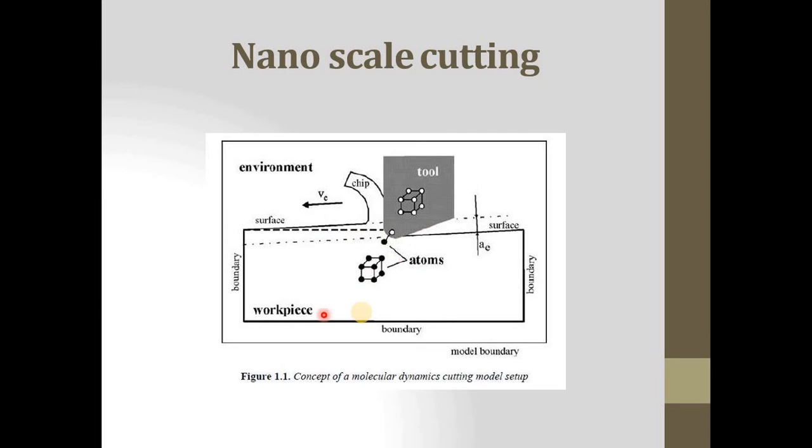So consider a crystal size. We're considering the crystal size of typical metals, which ranges between a few tens to several hundred microns in diameter. A single crystal, or what we call a single crystalline workpiece structure, represents a reasonable material structure for nanoscale cutting simulations.